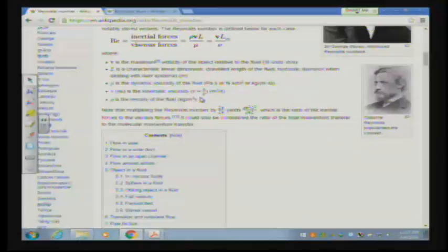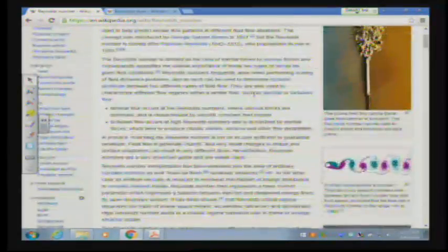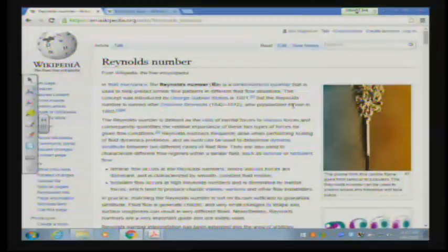So when we take a look at these ideas, we have to go back and remember what Reynolds number is, because Reynolds number will help us to determine whether we are in laminar or turbulent flow, and that will give us some other ideas about where the boundary layer is, how thick it is, what its relative thickness is to the thickness of the conduit or the dimensions of the fluid flow.